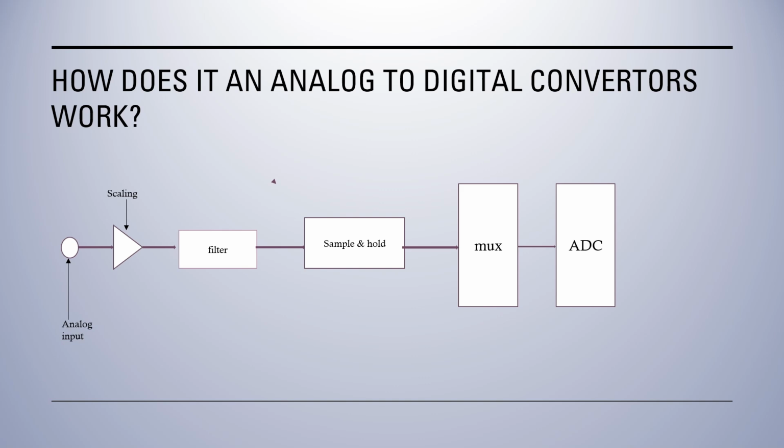Okay, there's a filter. Sometimes when the voltage goes into the microcontroller, when it's sensing, there's a lot of noise in there. So there's a high pass filter in case there's some sort of squeaky squelch, and there's a low pass where it doesn't want all the low garbage. So it wants to basically contain all the good stuff in a band pass type filter.